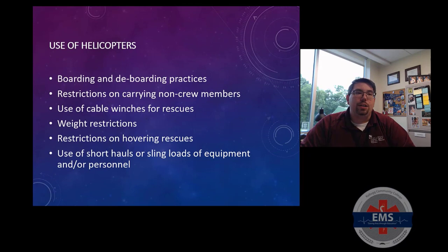Things like boarding and deboarding practices for safe loading and unloading of the helicopter. Again, we recognize from our landing zone class that we should never approach a helicopter where the rotor blades are moving, nor should we ever approach it from the rear tail fin. We know that there's going to be restrictions on what equipment they can carry versus potential crew versus non-crew members.